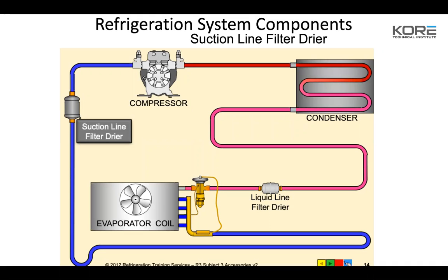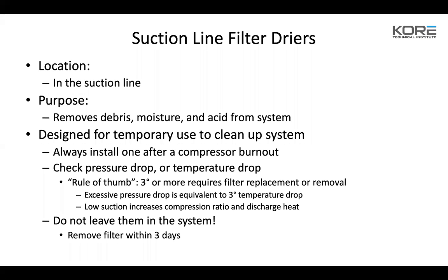Refrigeration system components, suction line filter dryers. So let's talk about suction filter dryers. The purpose for suction filters is usually on startup, or when a major component's changed out and they're trying to clean the system, they'll throw a suction filter dryer in there. Suction filter dryers are meant to be temporary. It's in the suction line. It removes debris, moisture, and acid from the system. It's designed for temporary use to clean up the system.